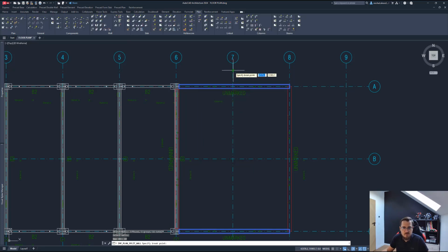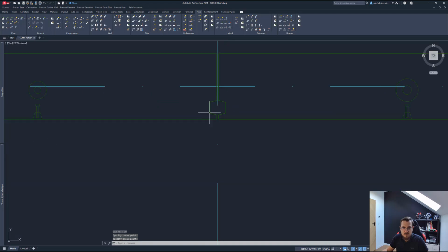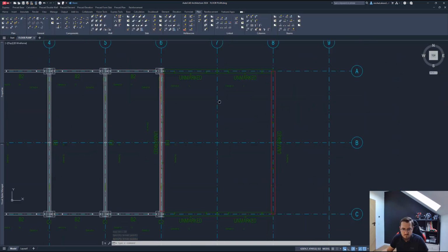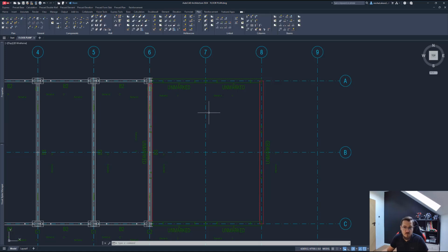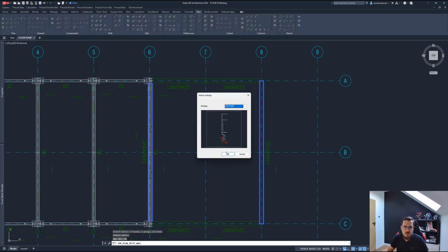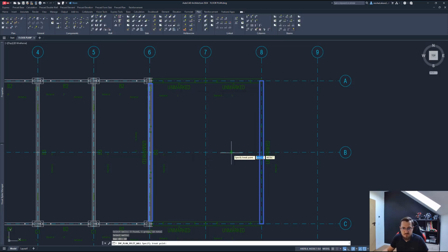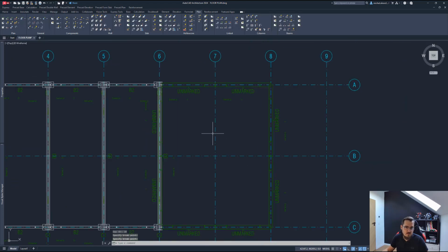And I'm just going to click here and accept that. You can see both the end cap has been applied and the walls, both on the top and bottom of the screen, have been divided. So let's do the same thing here and here. And the gap is again going to be 10 mil, and I'm going to use the same end caps. And like that, I'm just going to click on that midpoint line, and our axes are done. Okay, so that's one thing done.